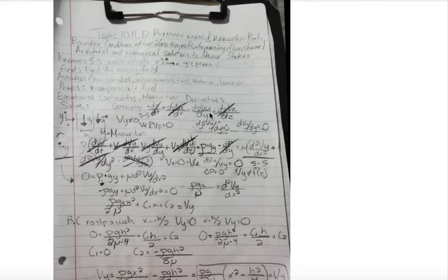Now when we do the y momentum balance, we write that all out, and now we start crossing out all these assumptions that were present. We knew that the flow was parallel, incompressible fluid, Newtonian, and laminar, and we knew there was no slip at the walls. So we know that Vx and Vz equal 0, so all those Vx, Vz terms cancel out. We know it's steady state, so dVy/dt goes to 0. And then we know that there's no pressure change, so delta P equals 0. And then we know that Vy dVy/dy is 0.